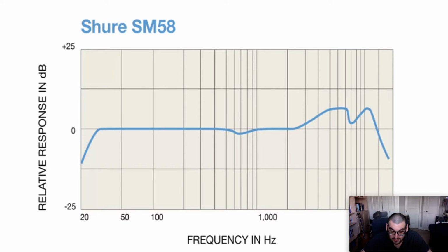And the bottom end kind of rolls off, kind of the areas that would be below the voice in typical situations. So as you can see in the end here, it just rolls off. So we have our peak at about 5,000 Hertz here. Okay, boom, and then it rolls off. Okay, for those lower end frequencies. We don't want those frequencies.